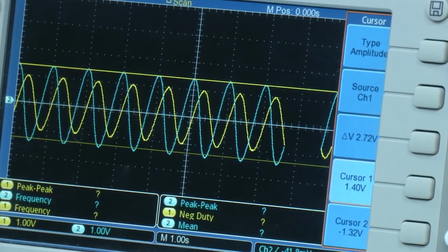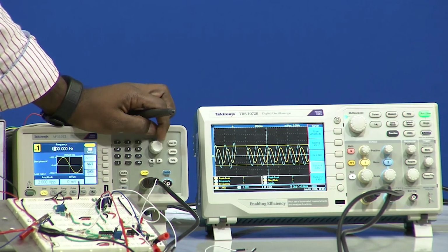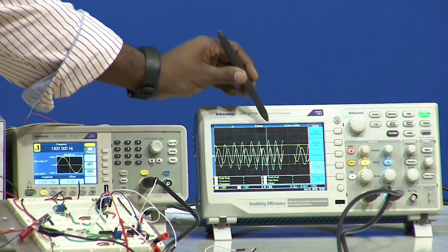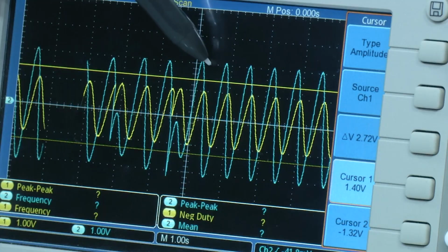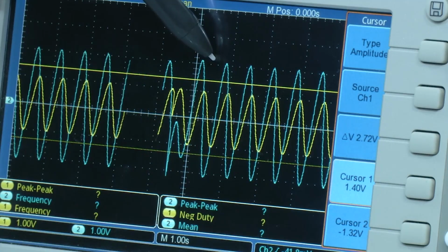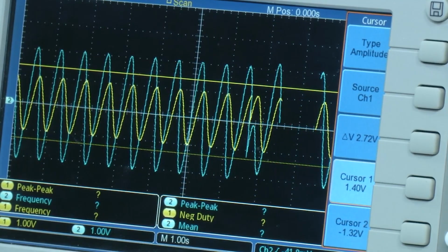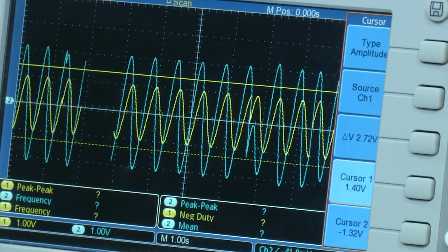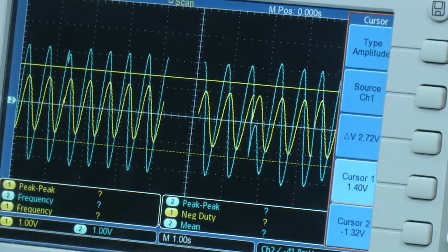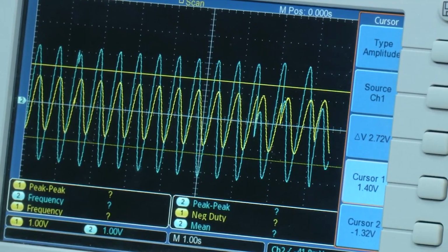Now, I will slowly increase, let me see what the change will be. 1.4 hertz right now, 1.5. Now, when it is at 1.5 hertz and you zoom in, the gain is higher than 2. That is what we observed in our simulation too. Increase to 6, even higher, 7 higher, and 8 even higher. So, I will slowly decrease the value.